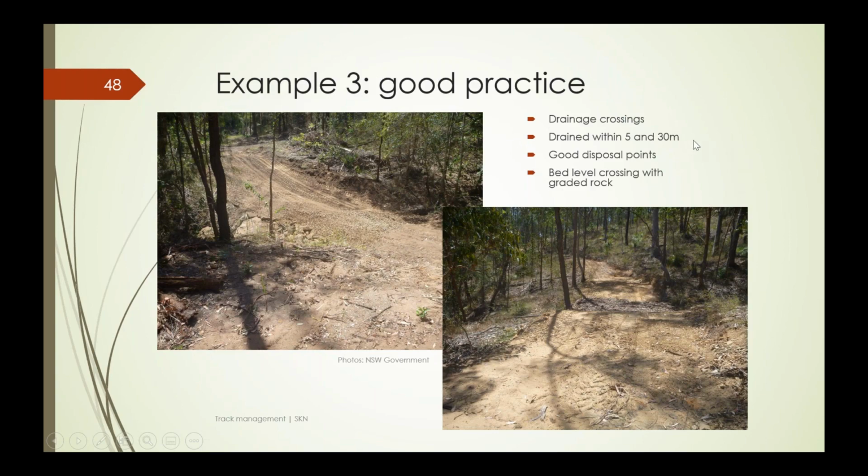So the good things here, we've got track drainage in place. We've got good disposal points, so the water spreads out rather than running straight into the drainage line. And the crossing itself is protected with graded rock.